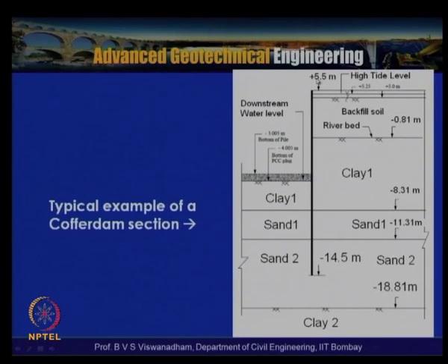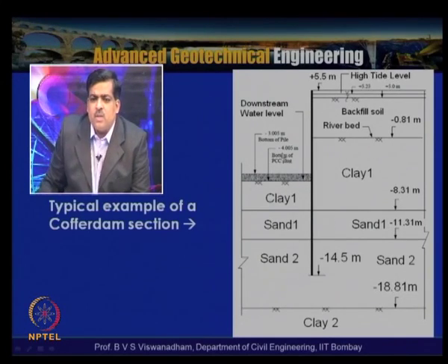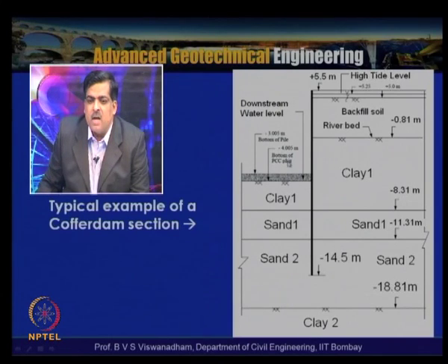In order to construct a pier foundation, what is intended is to construct a cofferdam, which is generally a sheet pile wall driven into the ground, and thereafter, after putting the necessary ties, the excavation will be done up to a certain level. Here in this case, there is a river bed, and above that a filling has been placed, and then this is the high tide level or upstream water level.